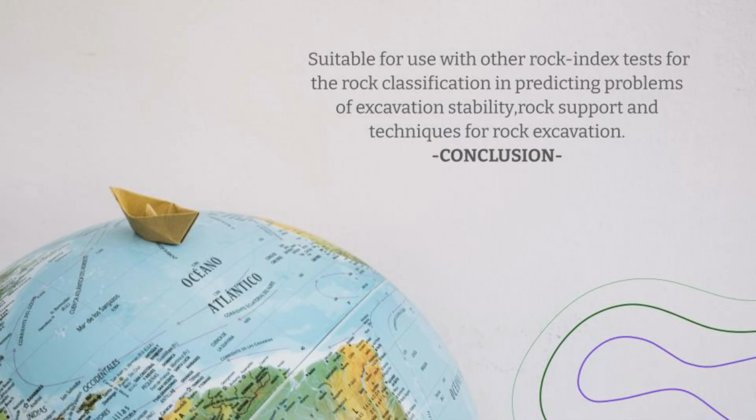In conclusion, this slake durability test is a very useful test with the main purpose of evaluating the weathering resistance of shales, mudstones, siltstones, and other clay-bearing rocks. This slake durability test is also suitable for use with other rock index tests for rock classification in predicting problems of excavation stability, rock support, and techniques for rock excavation.